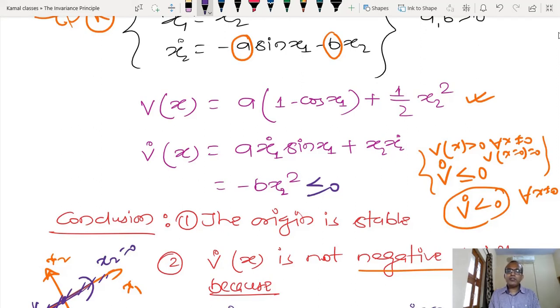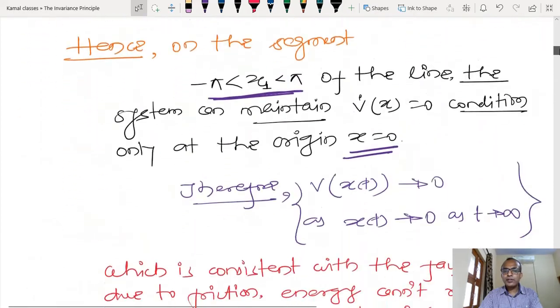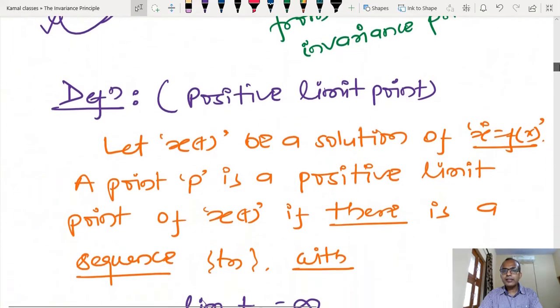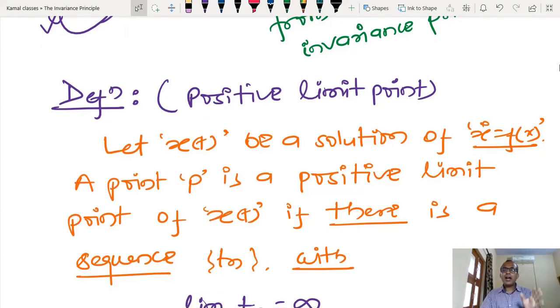Okay, if up to here anyone has confusion, then please let me know. Now I am going to first state some definitions to support this idea, and after that we will see what extra benefit we get. One benefit is obvious: I start with any Lyapunov function and check its rate of change. Even if that is semi-definite, I can talk about asymptotic stability. In parallel we will see what other benefit comes into the picture if I rely on the LaSalle's invariance principle. So some definitions are required.